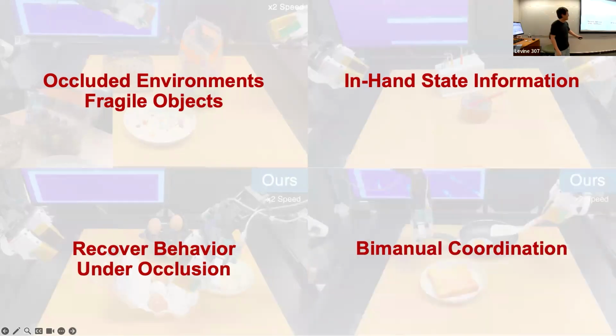What about the point cloud, with reflective materials and very tiny objects? The point cloud works well, no problem, except not very well for the grip demo, because the grip is very small. If your camera is very noisy, the noise will cover the grip's size, so that makes the point cloud very hard to distinguish. And you can also check this project's website, which shows the point cloud observations for different tasks.